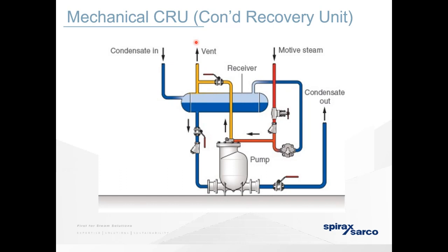Mild steel, though, has been the standard for steam systems for many years. Although it does wear, it depends on what process you've got. If you've got steam as an energy source for, say, heating vessels, which is not going to come into contact with any of your product, mild steel is fine. You will have more maintenance costs compared to stainless steel, but it's a lot cheaper.